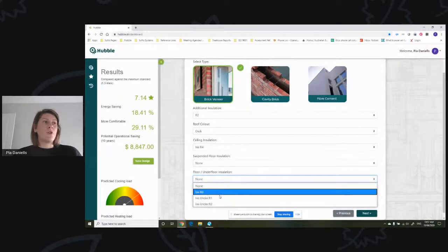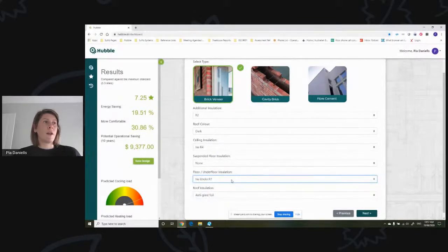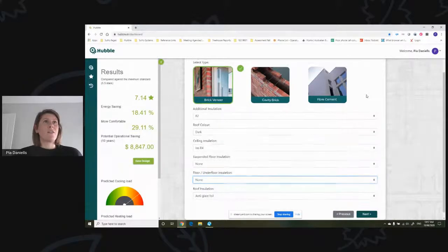So this does show something like adding floor insulation, so insulated concrete slabs that have polystyrene laid with the concrete over the top. You can see that as actually improving the performance of the building versus having a non-insulated concrete slab. So we can start seeing how the building performs with the change in those materials and the change in the specification.